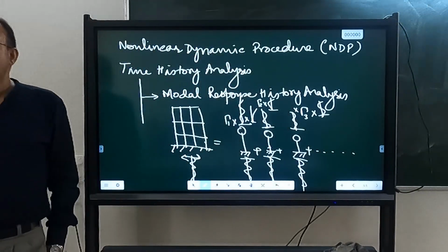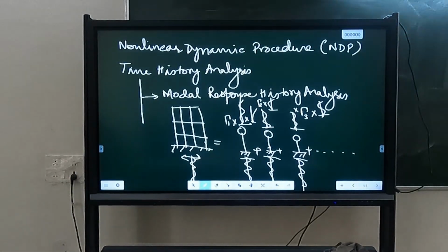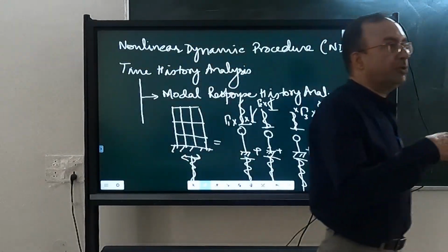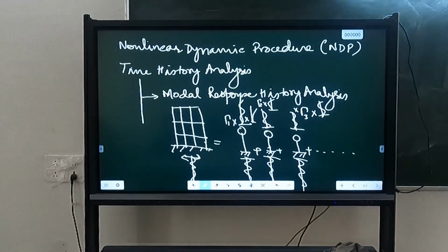So this is modal response history analysis. In modal response history analysis, we are doing time history analysis only, but we are doing time history analysis of single degree freedom systems corresponding to different modes, and we are adding them.